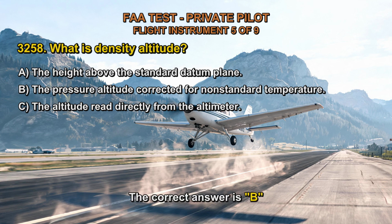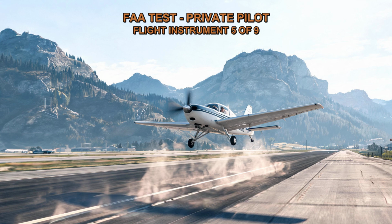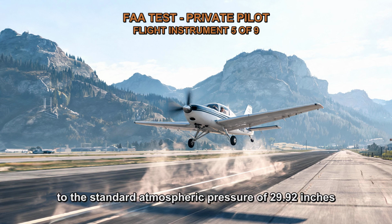The correct answer is B. Density altitude is a measure of the density of the air in relation to the standard atmosphere. It is calculated by adjusting the pressure altitude, the altitude indicated on the altimeter when set to the standard atmospheric pressure of 29.92 inches of mercury, for non-standard temperature variations.